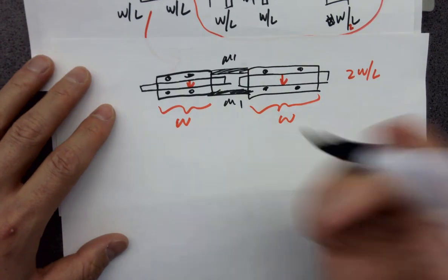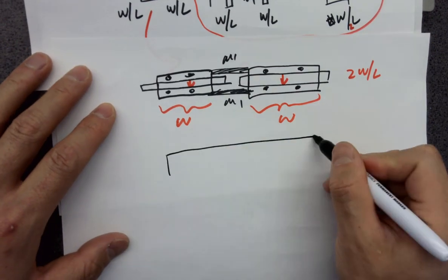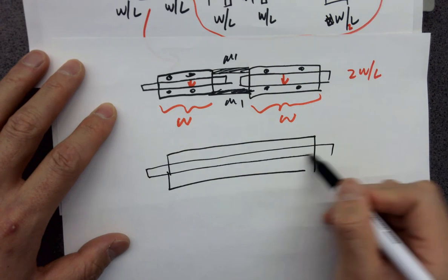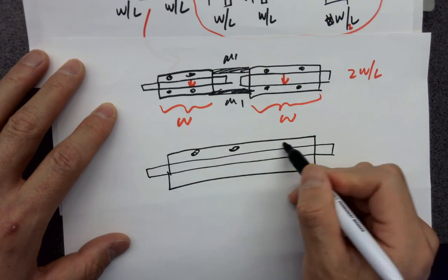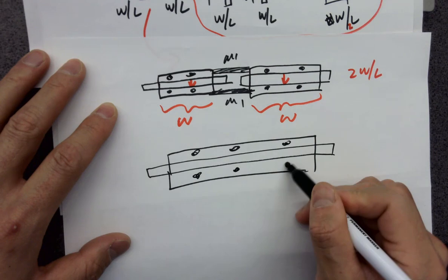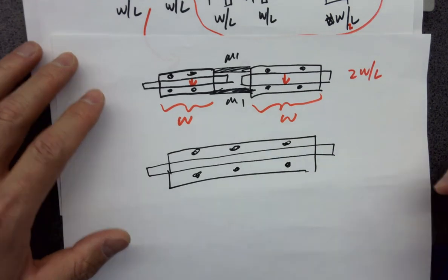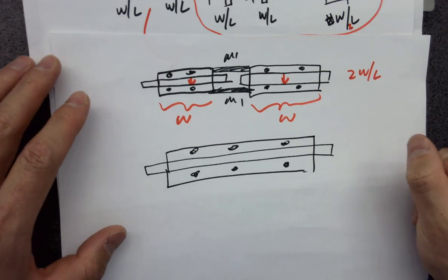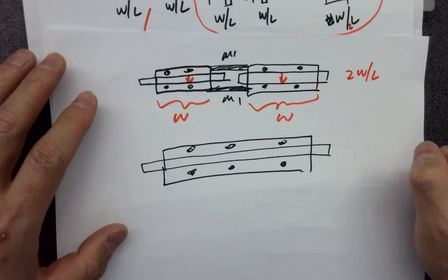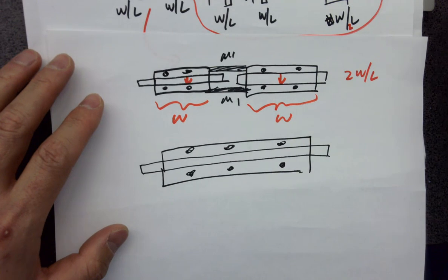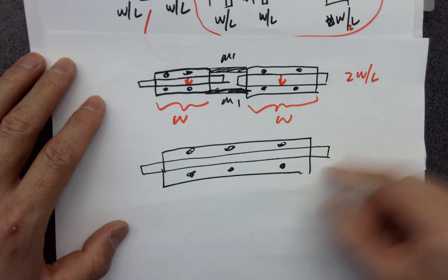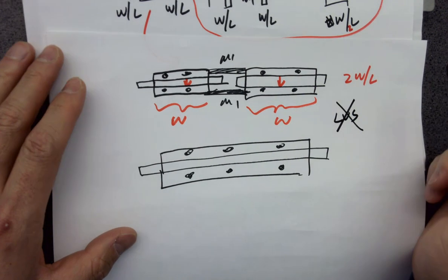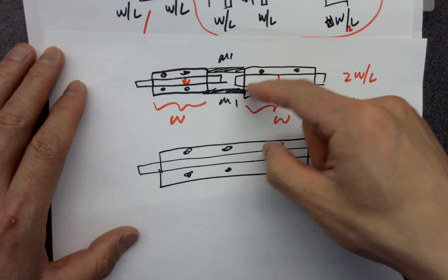I can use one bigger transistor to reach the same electrical property, okay? In terms of driving capability, the parasitic capacitance inside and everything, a lot of those things are equivalent. However, because there's just one gate, if you do an LVS, it won't pass because there are different circuits.